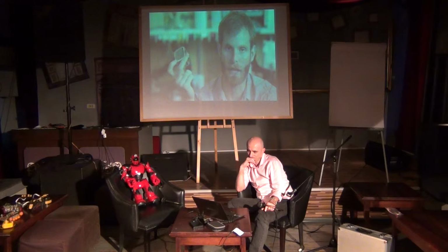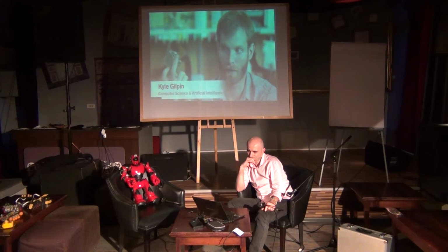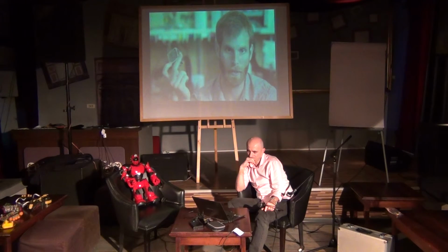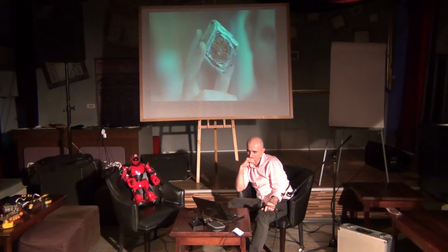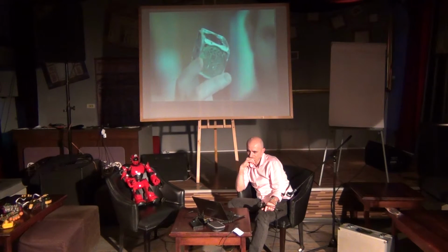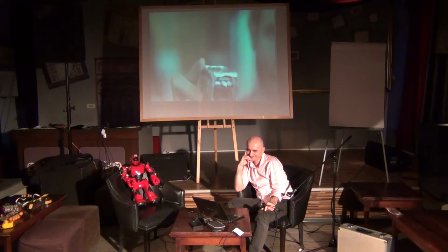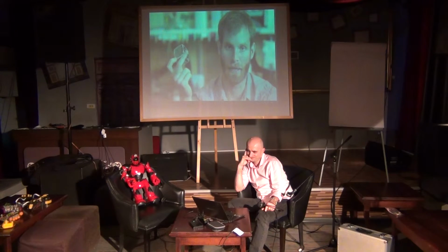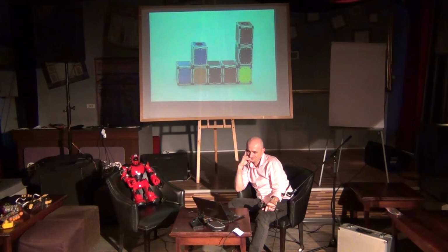So there were a couple challenges when we came to design the M blocks. One was fitting everything inside. So we have a relatively small volume, and we needed to fit a brushless motor controller, a flywheel, a braking mechanism, electronics, a radio, a battery. Additionally, we faced the challenge of trying to simplify and make the design as robust as possible. So we didn't want any external moving parts, we didn't want latches, we didn't want the cubes to change their shape, we just wanted simple blocks that were able to move on their own.